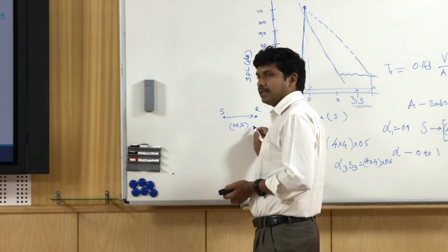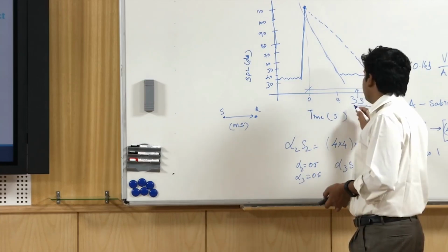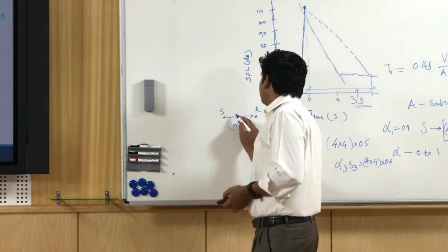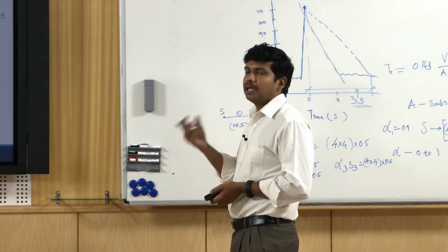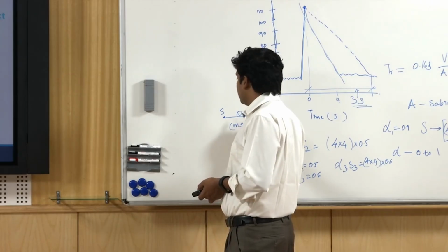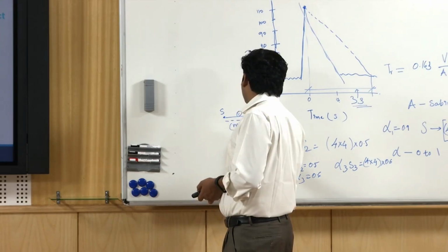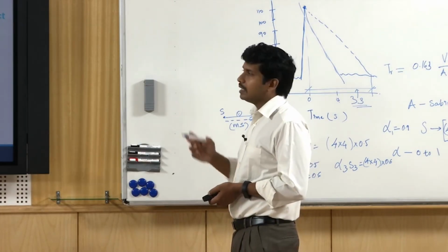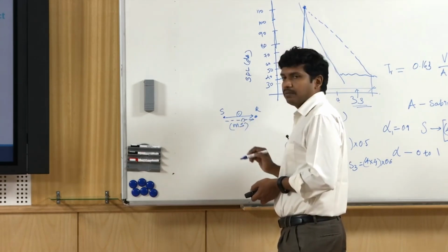But if you have a very long reverberation time, say 3 seconds, 4 seconds, then imagine you are clapping or spelling one word after the other. The first word reaches the person's ear in a few milliseconds, then the second word is spelt, but if the first signal has not decayed down, or the reverberation time is high, then this would start masking the second one.